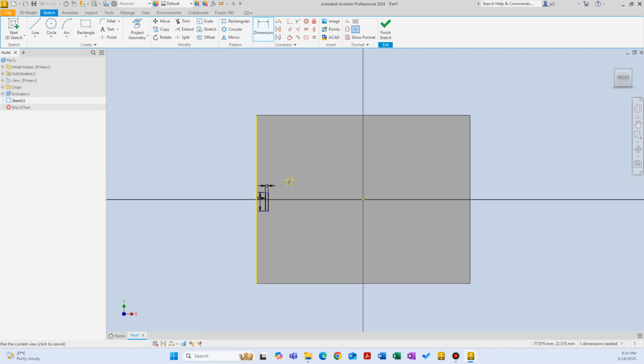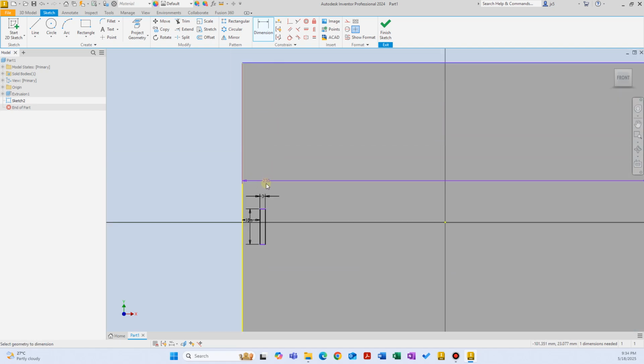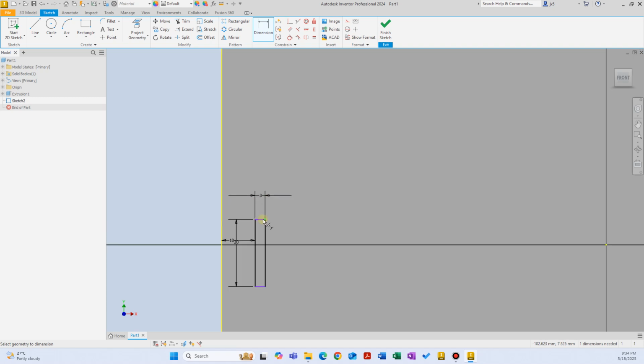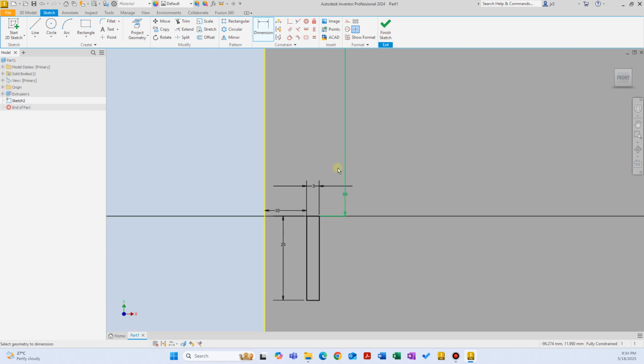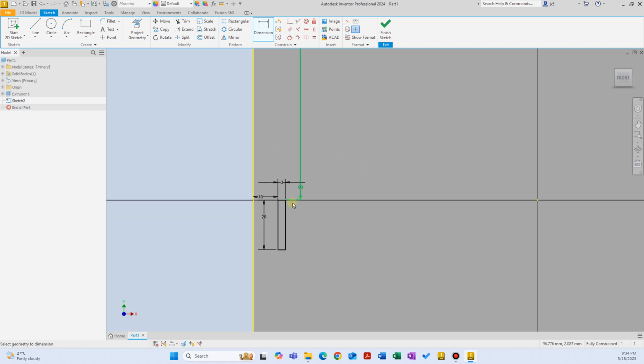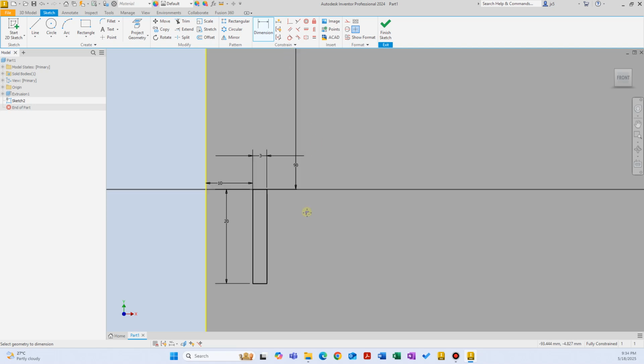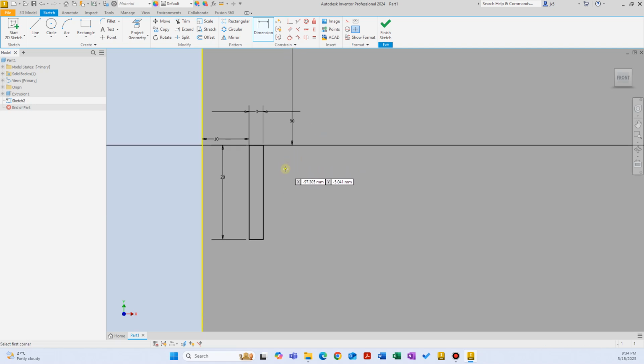And the only thing we haven't assigned is this edge to this edge, this height here, which is, let's call it 90 millimeters. And I can technically apply an extrusion to this and then do feature patterns, but I want to design the second tab as well. I want to be able to have two tabs, two extrusions, in which I can slide a toothbrush.